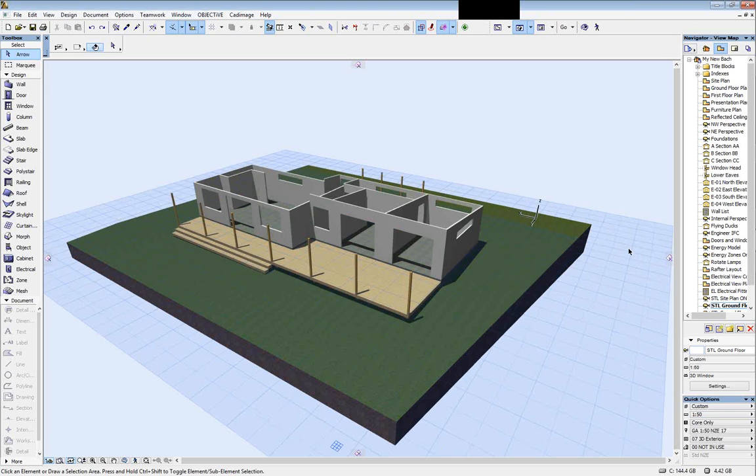So with that in mind, you can see that the doors and windows are removed because our 40mm aluminium joinery and our 10mm thick glass come down to 0.4 millimeters thick, and the 3D printer will simply refuse to print that. It will just turn out horrible. So much like you would actually make a model in real life, windows are left as just holes and openings, so it just illustrates where they are.